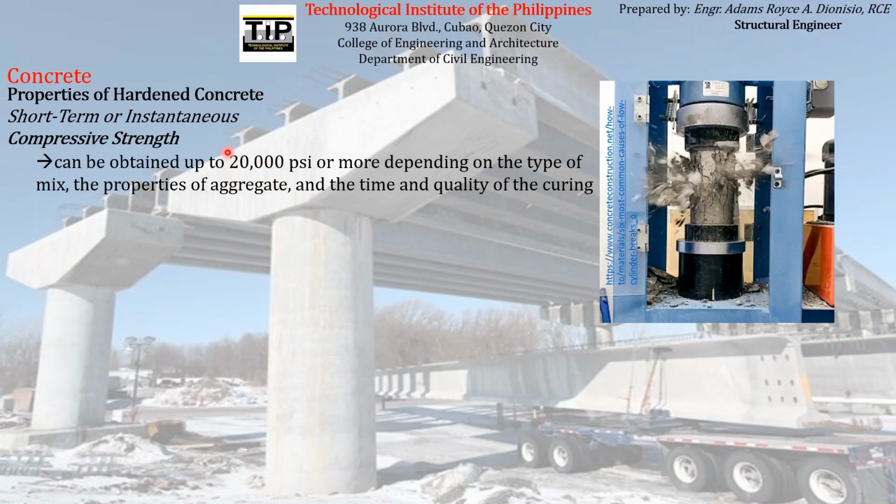Actually, concrete that has this high amount of compressive strength is usually called high strength concrete. Those high strength concretes are usually the materials being used in pre-stressed concrete because a normal strength concrete cannot withstand the high intensity of stresses occurring in a pre-stressed concrete, especially coming from the pre-stressing reinforcement.